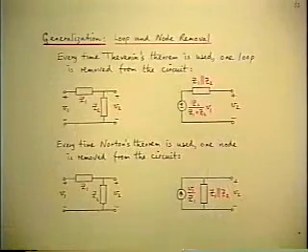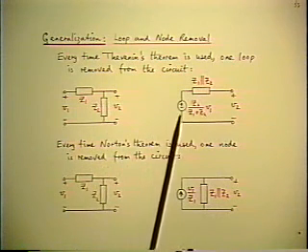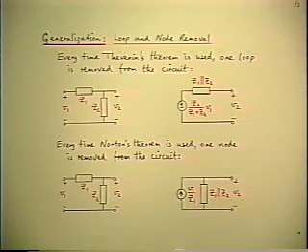Now, I don't know how often you use Thevenin's and Norton's theorems when you're doing your analysis. I would guess they're about the only theorems you ever use much, but maybe you could use them to advantage even more. If you simply remember that the value of the theorems is, every time you use Thevenin's theorem, you get rid of one loop. Every time you use Norton's theorem, you get rid of one node. And that means that if you start with a multiple loop, multiple node circuit, you can use those theorems in succession, and you can gradually reduce the complexity down maybe to a single loop.